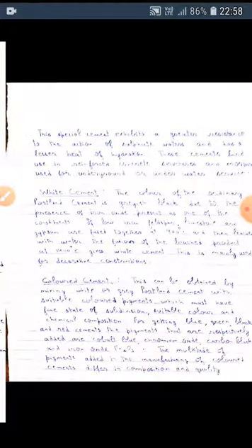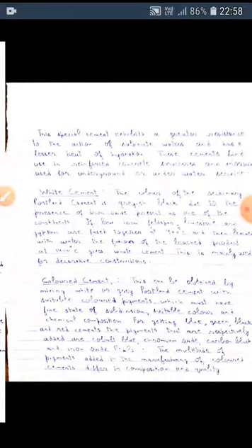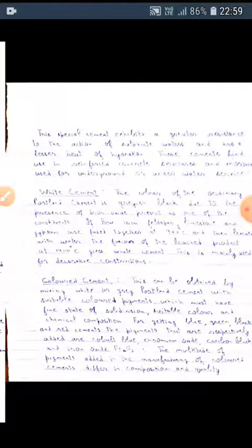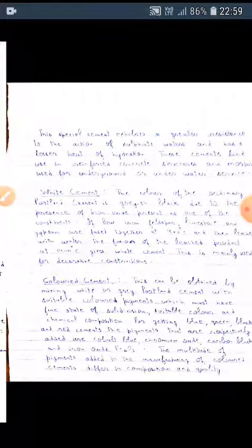It should be noted that burned dolomite is used as an alkaline exciter of slags. For a basic slag, the temperature range is 800 to 900 degrees centigrade, causing complete decomposition of magnesium carbonate and partial decomposition of calcium carbonate. For acid slag, the temperature ranges between 1000 to 1100 degrees centigrade, resulting in complete decomposition of magnesium carbonate as well as calcium carbonate.